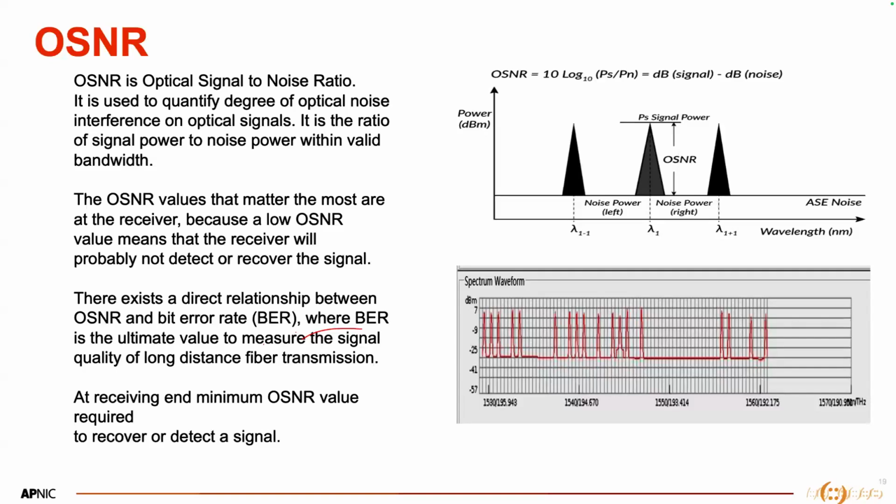Yeah, it might, but you know what? OSNR doesn't fall onto fiber solely, because when you are talking about fiber, you are focusing on the optical power. What is OSNR? OSNR is the optical signal to noise ratio. Fiber is a passive thing. It can hardly add any noise to the signal. So your noise will be added from your active components, like amplifiers.